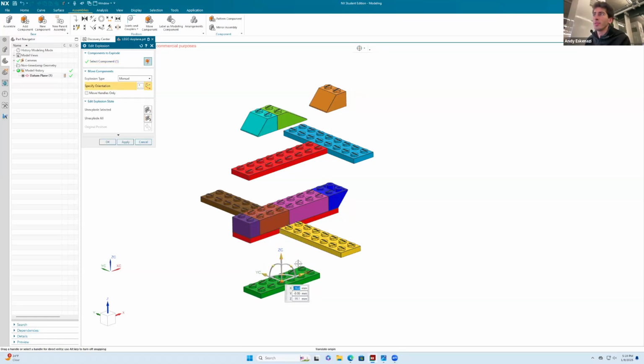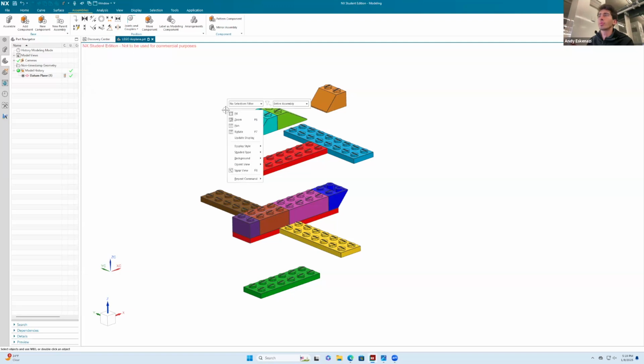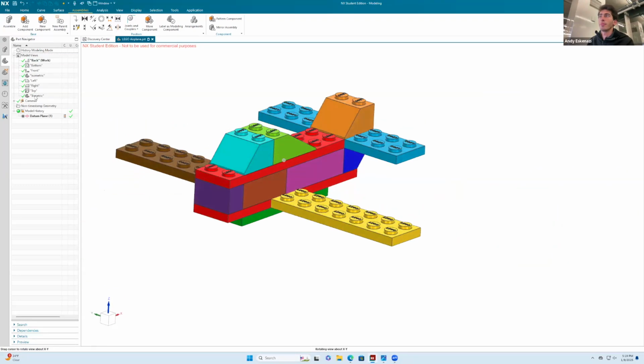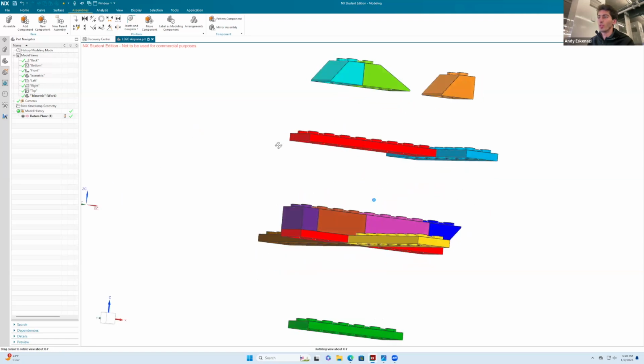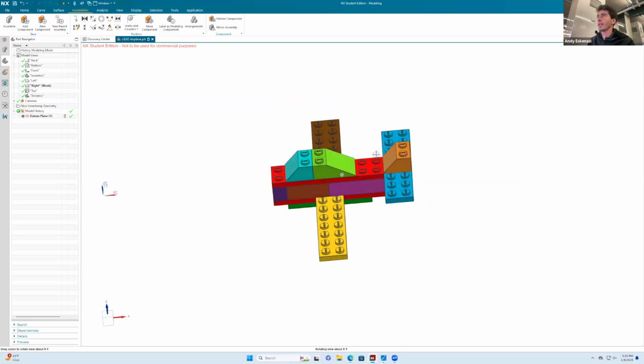So the nice thing about this Lego assembly is that I'll say, okay, actually, yes, I did do okay. And yes, now we just left our exploded view, right? In fact, we could potentially save this as a view because otherwise, I believe, delete explosion, invisible view. I can say close in here because if I were to go back to model view, I go to back, you see how it disappeared. We no longer have it, so it was saved in the trimetric view in here. If we go back to right, we have again our exploded view.